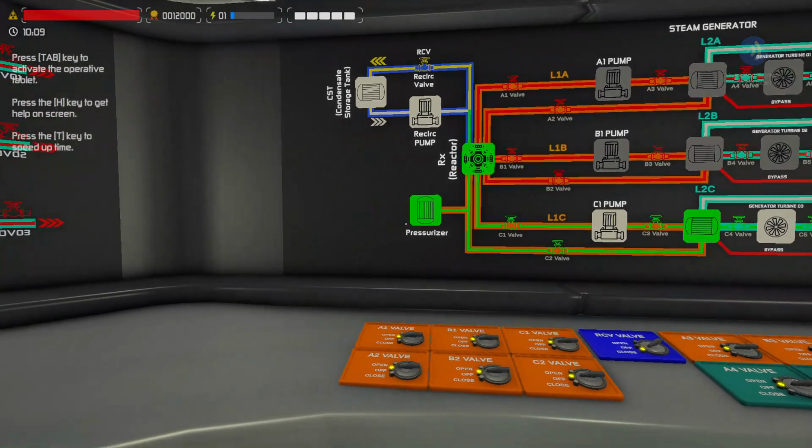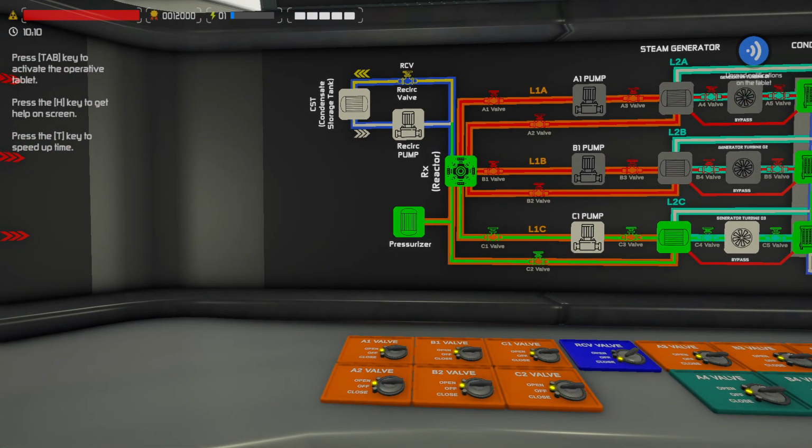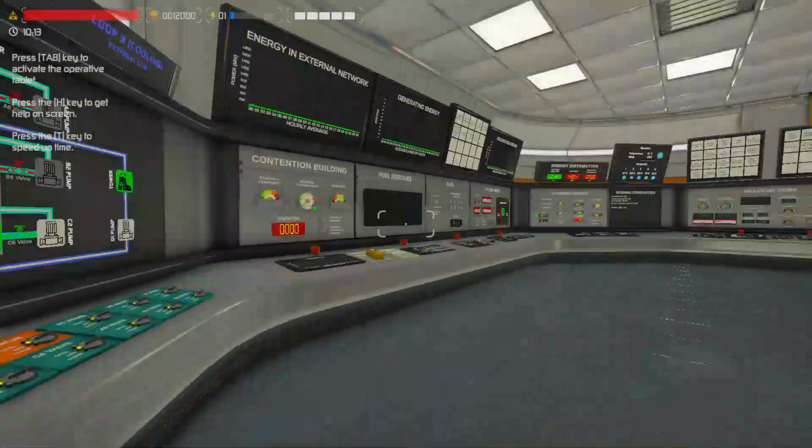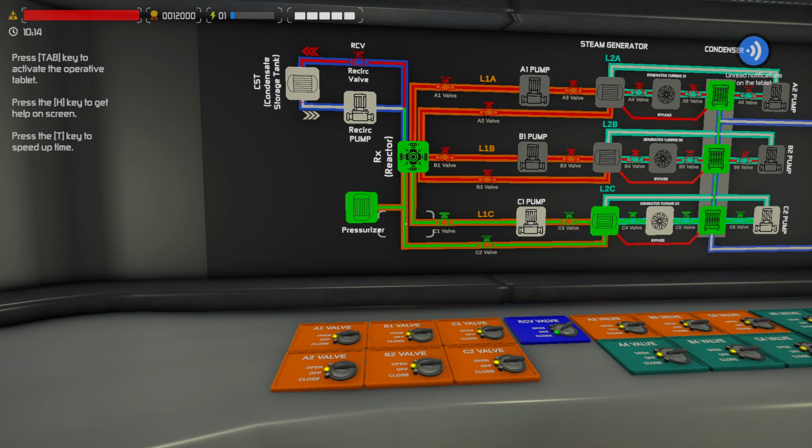Okay, the pressurizer is basically the backbone of the pressurized water reactor. The pressurizer's only job is to create a steam bubble inside of it to control the pressure of the rest of the reactor so that the reactor liquid remains subcooled. This reactor operates at 360 degrees Celsius, which is 260 degrees above boiling temperature. So if this was at atmospheric conditions, your reactor would boil.